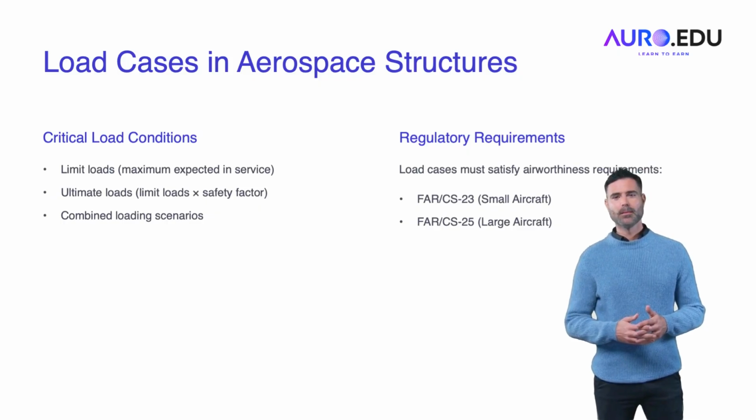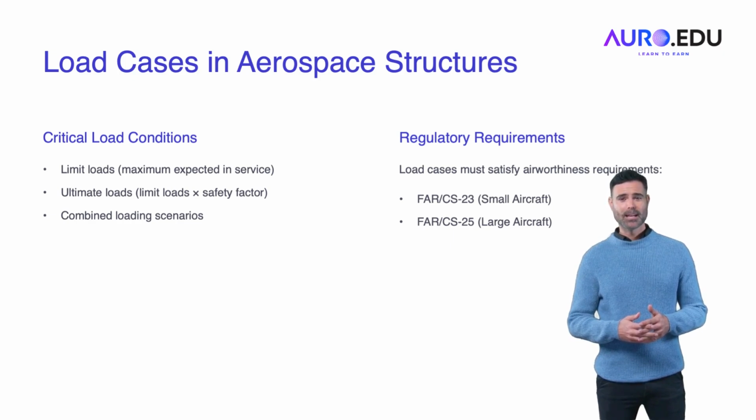Compliance with aerodynamic load distribution, such as pressure distribution from CFD, computational fluid dynamics, is crucial for simulating real-world flight conditions. Regulatory requirements such as FAR CS23 for small aircraft and FAR CS25 for large aircraft mandate specific load case simulations to ensure structural safety. Proper application of loads ensures that FEA results accurately reflect the performance of aircraft structures under realistic operating conditions.